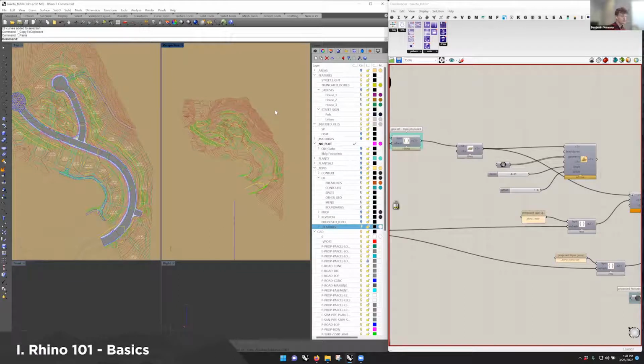A few things to remember about dealing with geometry from Rhino into Grasshopper, but it also applies very much to Topo Kit as well, is making sure you don't have, we've only run into this a few times, but making sure you don't have duplicate line work. Sometimes surveys come in really messy and you end up with contours that are doubled up. Do you have a comment, Chris?